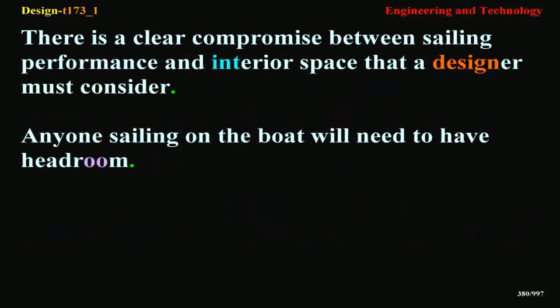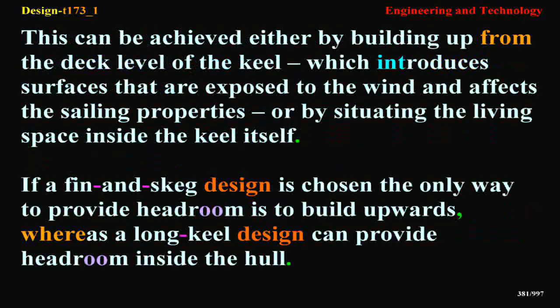Anyone sailing on the boat will need to have headroom. This can be achieved either by building up from the deck level of the keel, which introduces surfaces that are exposed to the wind and affects the sailing properties, or by situating the living space inside the keel itself. If a fin and skeg design is chosen, the only way to provide headroom is to build upwards, whereas a long keel design can provide headroom inside the hull.